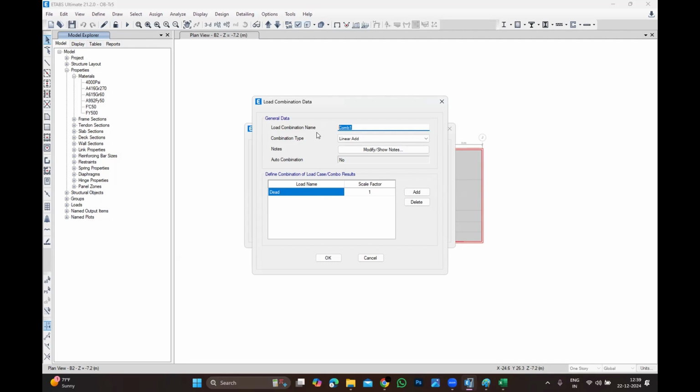Imagine the moment of inertia. If you multiply the moment of inertia with the height, you'll get huge stiffness, rather than talking about 400 by 800, 400 by 1000 columns. Those are frame elements. You will get a moment of inertia, but compared to the core wall, it is small, because of the length of the core walls. That is the reason sometimes in a high-rise building the wall thickness itself, the core wall especially, the shear wall, goes 500, 600, 700, 800. These are all things to control the drift especially.